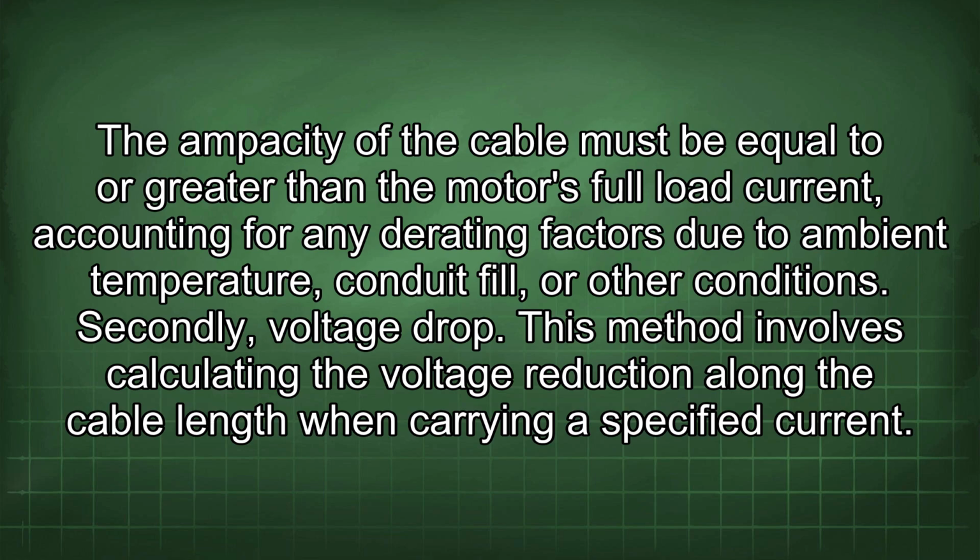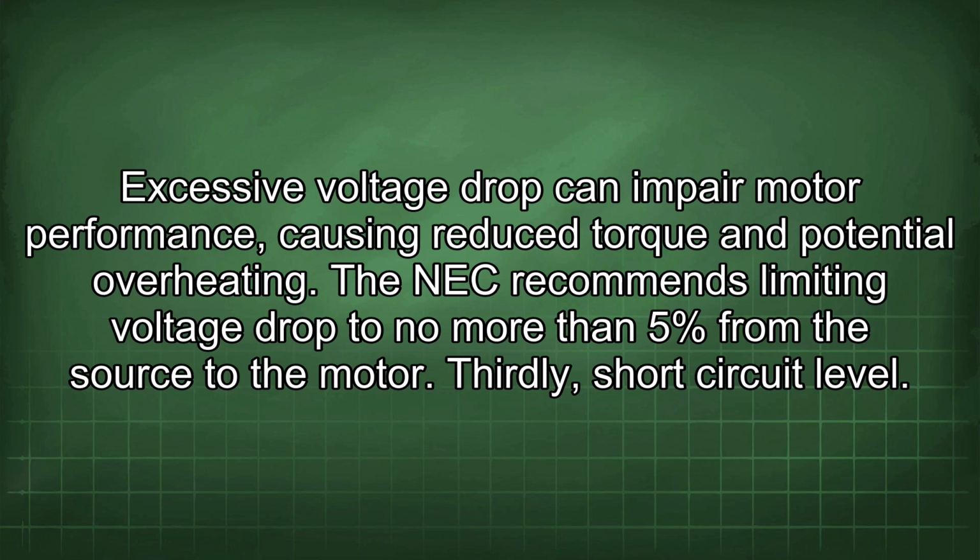Secondly, voltage drop. This method involves calculating the voltage reduction along the cable length when carrying a specified current. Excessive voltage drop can impair motor performance, causing reduced torque and potential overheating. The NEC recommends limiting voltage drop to no more than 5% from the source to the motor.